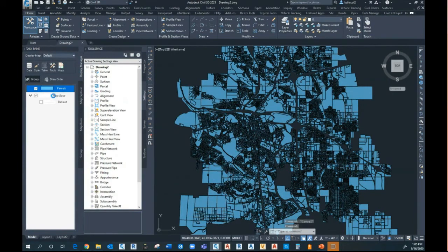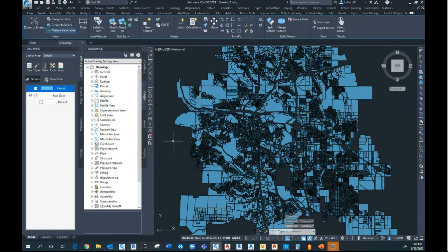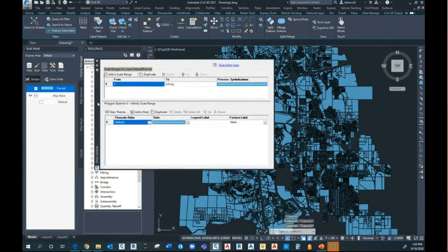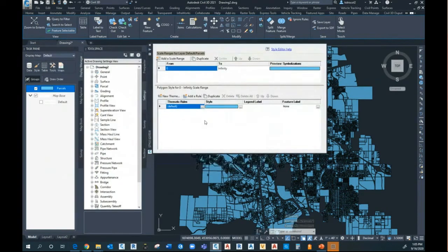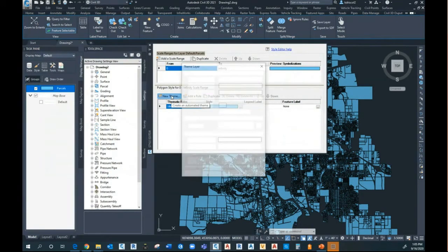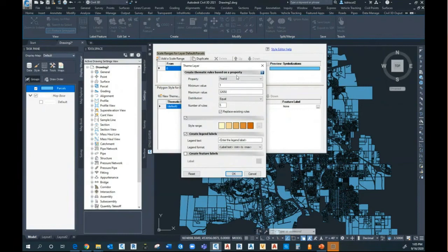If I picked on parcels, I can also go in and stylize that data based upon those attributed objects. So if I came in now, I can create a new thing. This new thing, based upon the object data, I can pull in specific properties. Well, I can say I want to display based upon land value from 0 all the way to $5 million, equally distributed.